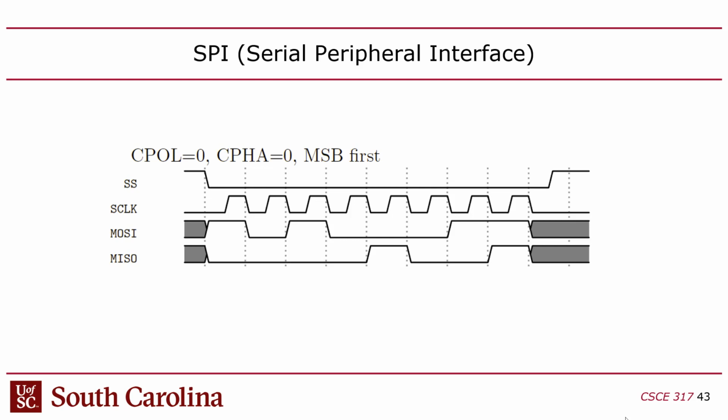The idea is that every time you initiate communication, you send data in both directions. The MOSI sends it one direction, and MISO sends it back. So what you have is an exchange, and this is called an SPI exchange. Every time you do communication on SPI, for every bit I send, I get a bit back, right? It's like I send you 8 bits and I get 8 bits back. So this whole thing is called an exchange. I want to emphasize that, okay?